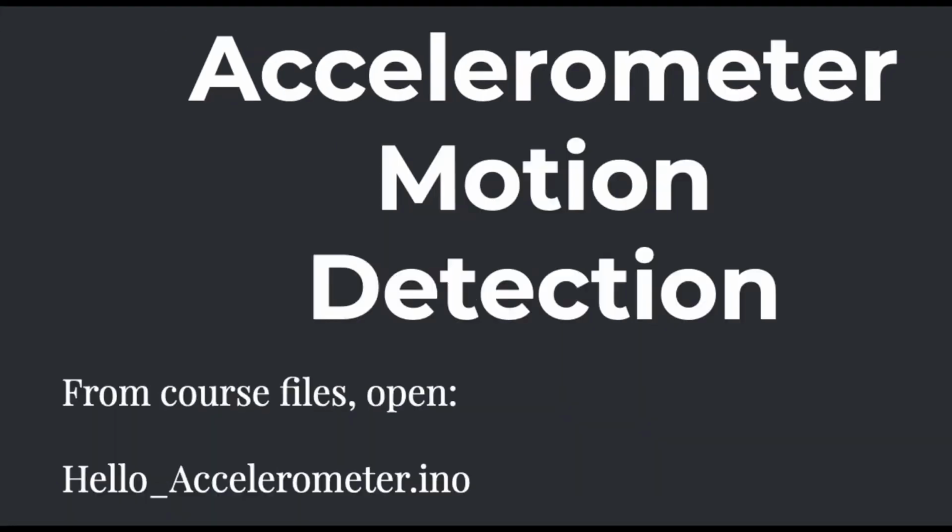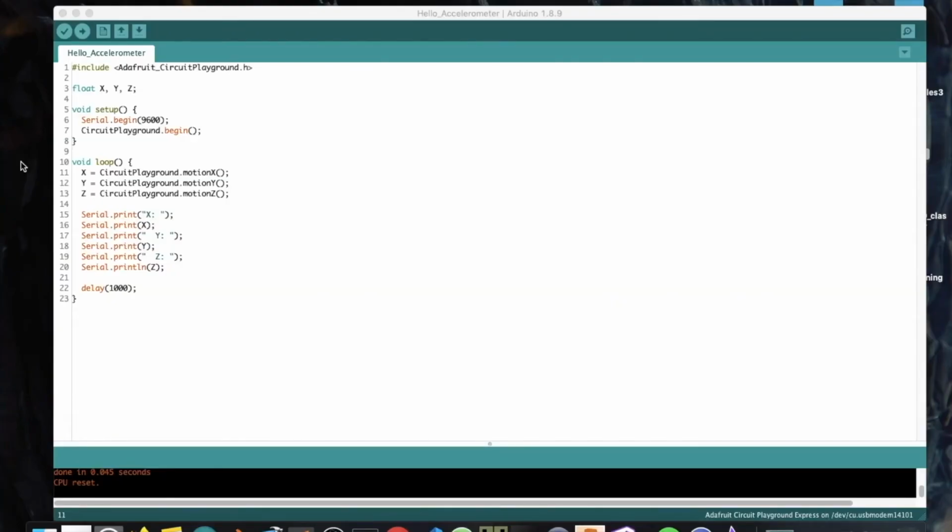From your course files, open Hello Accelerometer. Open the file Hello Accelerometer and check out the built-in 3-axis motion sensor on the Circuit Playground Express. As you can see, reading motion data from all 3 axes is very easy. It's just 3 different function calls. And then we're just printing the values. Note that motion detection is always relative to the position in which the Circuit Playground starts. You can't get objective position data from an accelerometer since it's more about motion than location.